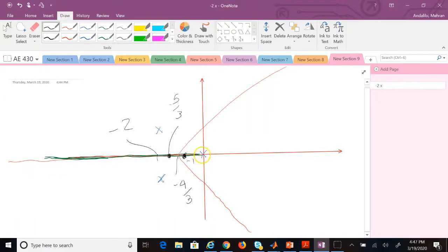So if I draw them, one branch comes like this. It comes from 0, the first pole, to the breakaway point and then gets off. And as k gets bigger and bigger, ultimately it will fall onto the asymptotes. The other one is doing exactly different, right? So that's one of them.